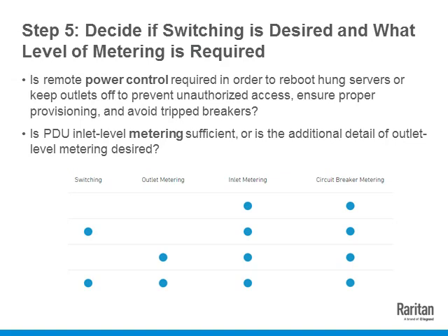How do we make sure what we meter at the inlet level also corresponds with what's being drawn at the circuit level? You have circuit breaker metering. When you have a power strip that has lines coming in and you have them split into 3 or 6 or 12 circuits within, branch circuits, we meter each one of these branch circuits, and the net total of that should add up to the inlet metering value.